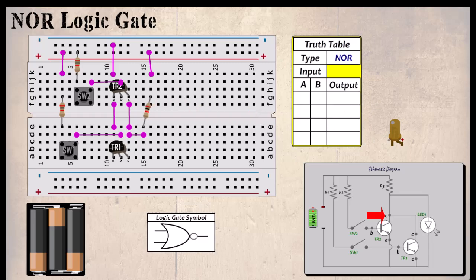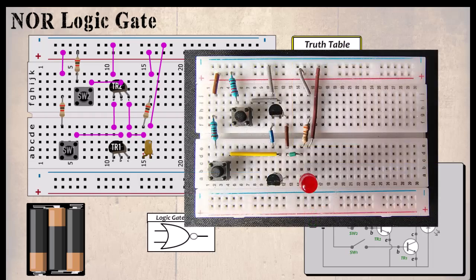The LED is connected from the collector of both transistors as well, but remember that this device is polarity dependent, so we need to reverse its connection. The other end of the LED is connected to the negative rail, so we will fit a link between the negative connection of the LED to the negative rail. We can see this in our practical design.